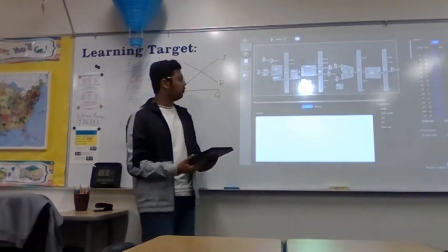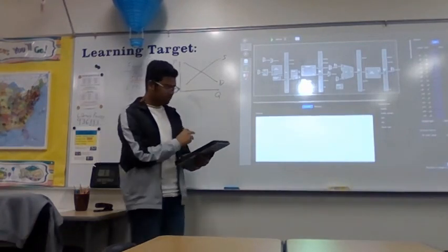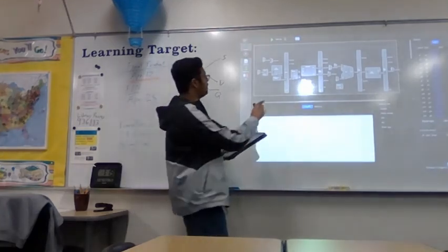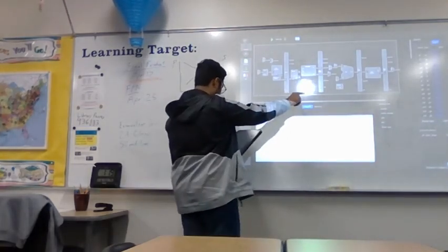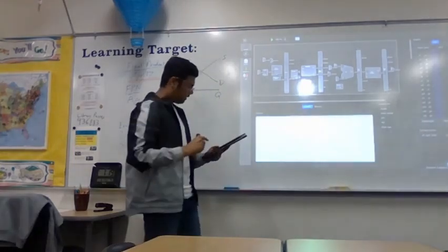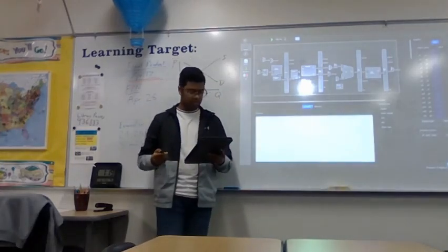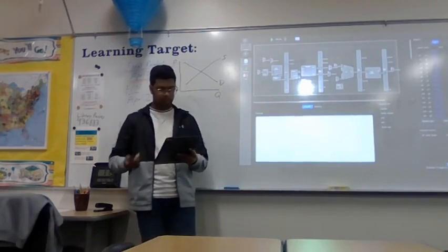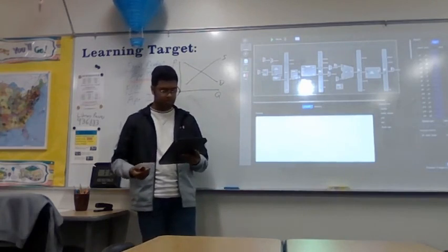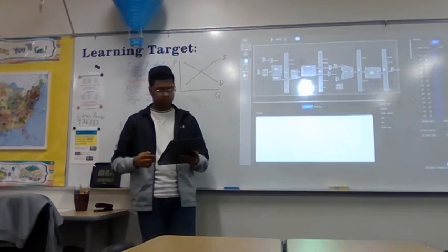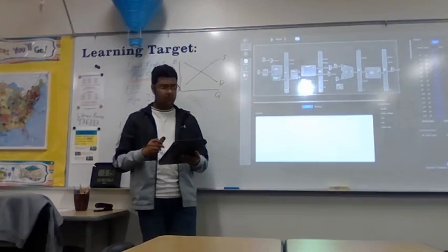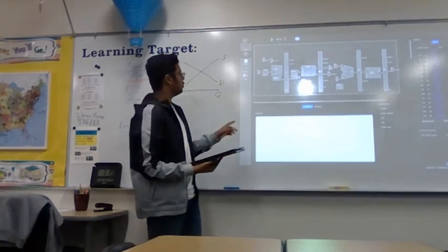All of my experiments were conducted in a simulator. This is the five-stage RISC-V pipeline simulator, and it shows everything: the instruction fetch, the execute, the memory, and the write back. The interface shows instructions flow cycle by cycle. I could see when a register was written, observe a read after write hazard, and watch a stall appear in real time. I could toggle the data forwarding on and off. Most importantly, I could measure exactly where these stalls were.